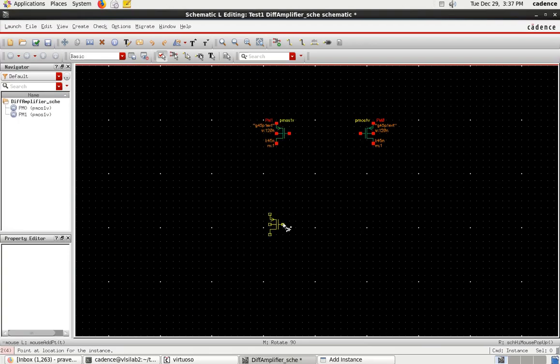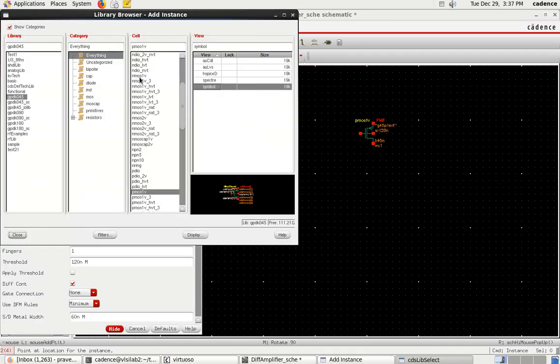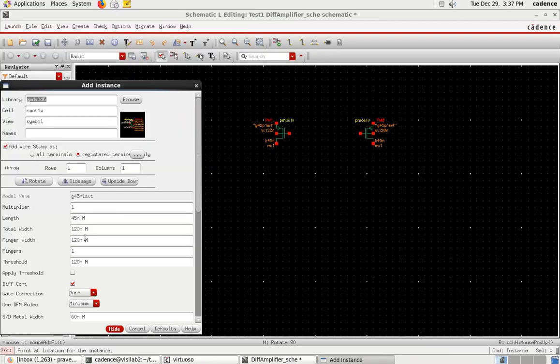Next I need 4 NMOS. I'll go to add instance, I'll browse, and I'll select NMOS. So NMOS I need, so just close this.